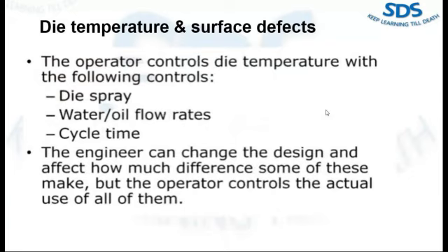The machine operator is really in control of the die temperature. It is controlled with die spray. How does the machine operator control die temperature? See, with the die spray, water and oil fluid.